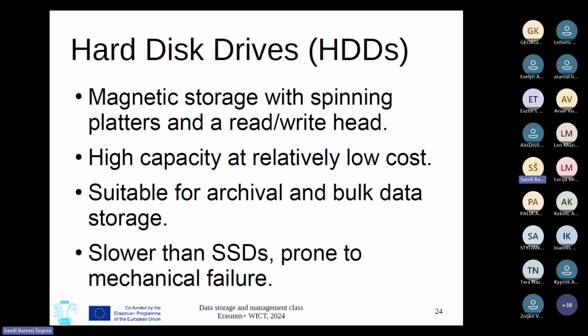So you have, for example, one of the servers that we have here, you have, let me see, 6 times 4, 24, 28 hard drives in it, and in a single rack, in a single enclosure, you have maybe 10 of those servers. You have 280 drives, and the vibrations of the surrounding hard disk drives can actually damage the hard disk drives, so they can actually destroy themselves when you have a lot of them working together.